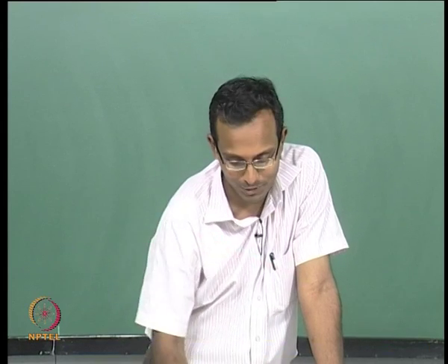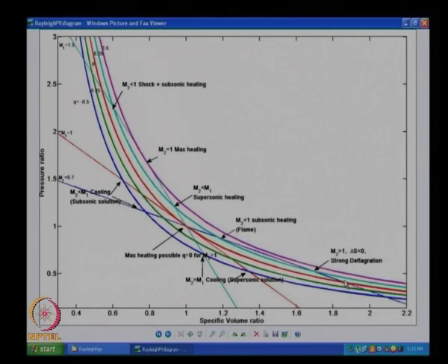That is that particular situation, and so that particular solution of the subsonic Rayleigh line cutting with this red curve for Q equal to 0 is not possible for us. That is one thing. And on the supersonic side, it does not go at all. That is on the other side, it does not go at all. There is only one possibility for Q equal to 0.